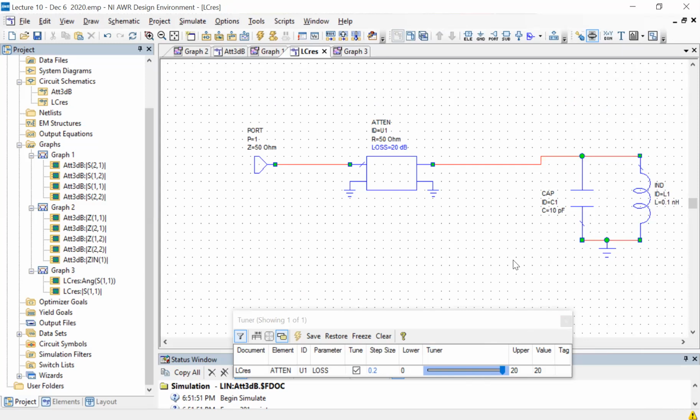So any loss being experienced must be due to something in between and not in the device. But what if you are actually trying to measure the magnitude reflection coefficient of the object at this end? Then this kind of an attenuation, like 20 dB, basically completely masks the reflection here. And this is connected to what we discussed yesterday in a different context: when you have a large attenuator, it basically looks like 50 ohms on this side, and it doesn't matter what is on the other side, because the signal from that other side is barely going to make it back here.